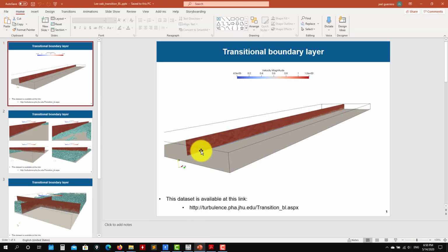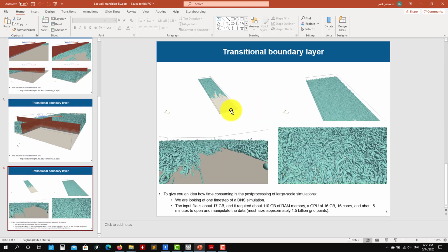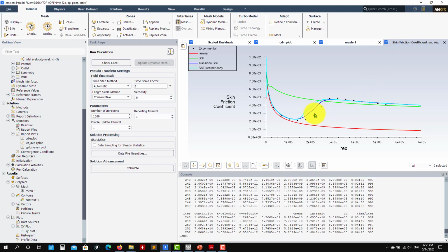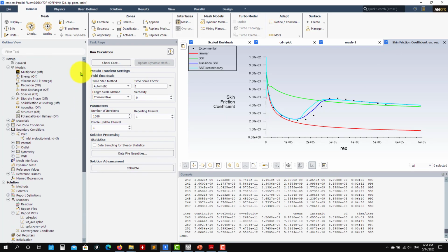And just to show you also the solution. Here we're just working with a 2D case, but basically we're doing this coupling, and you have the solution here. Let me put it here, and see here that you have laminar, then you have the hotspots and all those waves that are growing, and then you have the full onset of the turbulent flow. So basically this is what we're trying to model. What you're seeing here would be the full DNS solution. So let's work on this case. You can download the experimental results; you also have them in the data files on the website.